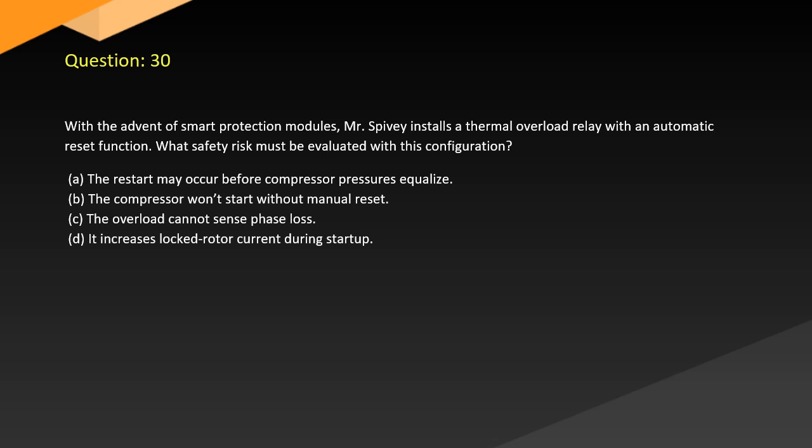Question 30. With the advent of smart protection modules, technician Spivey installs a thermal overload relay with an automatic reset function. What safety risk must be evaluated with this configuration? A. The restart may occur before compressor pressures equalize. B. The compressor won't start without manual reset. C. The overload cannot sense phase loss. D. It increases locked rotor current during startup.